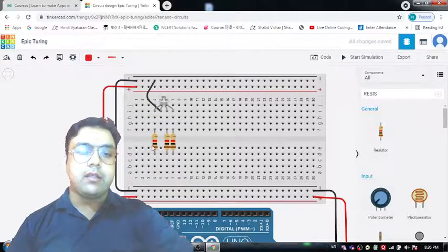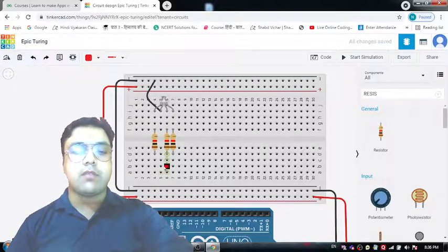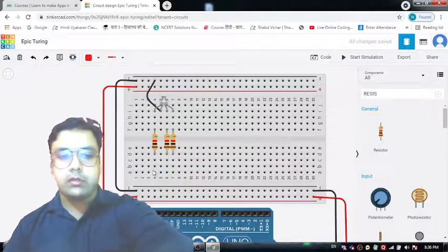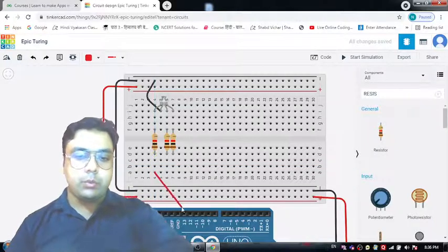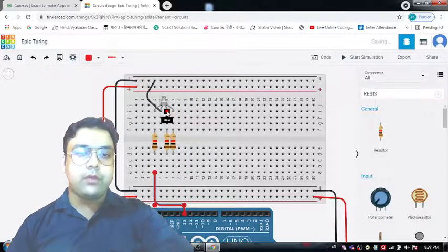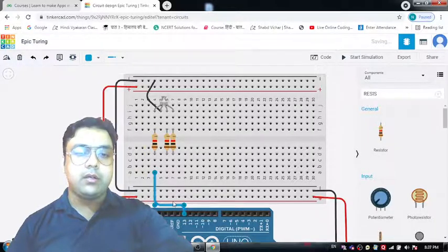For connecting this resistance, which is connected to the red point of this RGB, with one of the free points, rather, I should say, like this, present on this Arduino Uno R3 board. Then for this blue point, let's use the blue wire.